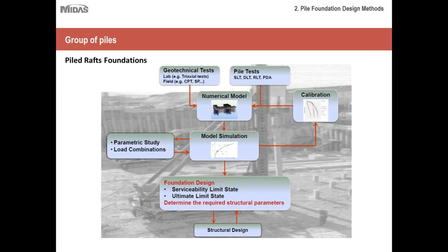So based on those forces and results that you obtain from the simulation, you have to check based on the code's standards whether the pile foundation or the pile raft foundation is meeting the serviceability limit state requirements and the ultimate limit state requirements. And this part of the job is performed usually by structural engineers.